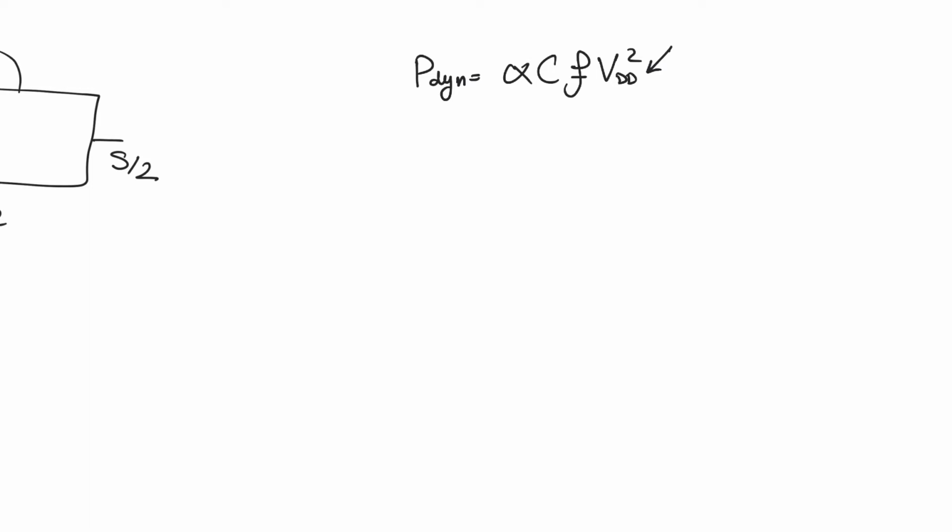But we also have to notice that the operating frequency, which is inversely proportional to the propagation delay in the critical path, is directly proportional to VDD as well. So reducing your supply voltage will also reduce your operating frequency, which would decrease your throughput. So you have to think about it carefully.